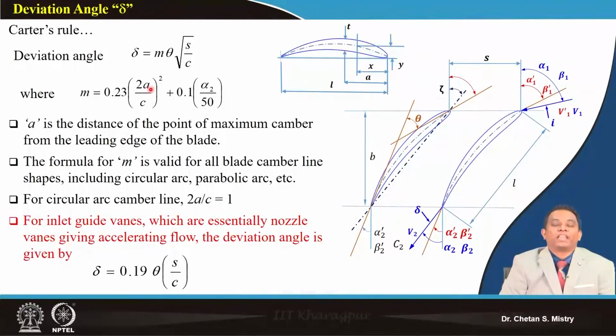So today we have discussed how we move with the change in incidence angle, and what parameters affect the incidence angle. We realized that mass flow rate, speed, Mach number and Reynolds number are the flow parameters that change the incidence angle.